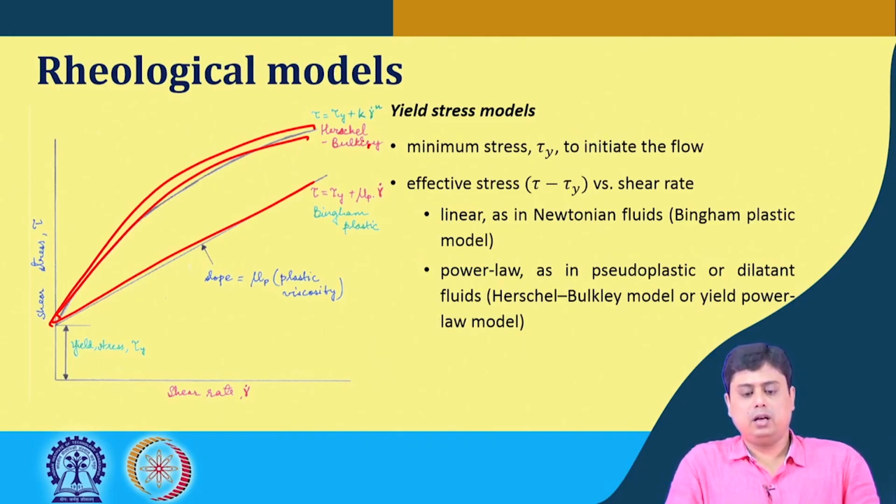But before I conclude my talk today, let me summarize. We started the discussion on the power law liquid velocity profile and how to estimate pressure drop in such a case. The pressure drop can be obtained directly from the theoretical expression or by the friction factor correlations. To know the friction factor, we have to understand the flow regime.